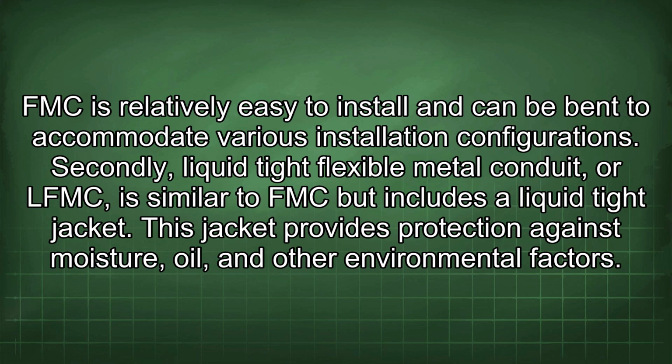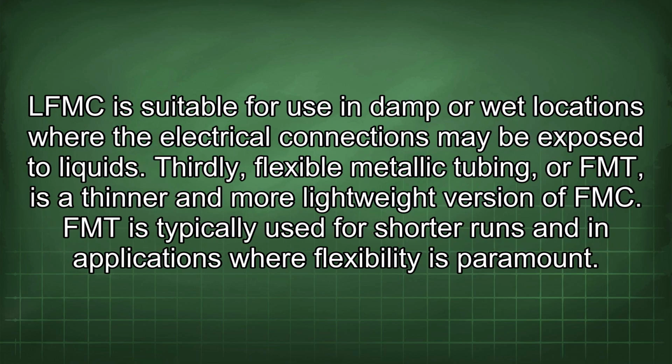Secondly, liquid-tight flexible metal conduit, or LFMC, is similar to FMC but includes a liquid-tight jacket. This jacket provides protection against moisture, oil, and other environmental factors. LFMC is suitable for use in damp or wet locations where the electrical connections may be exposed to liquids.